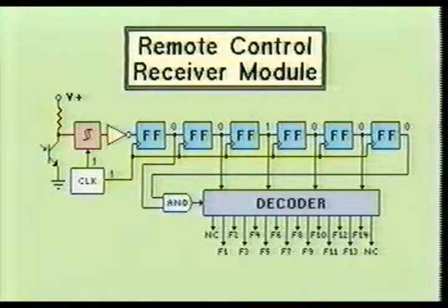The circuit scenario just explained is one of many possible methods manufacturers use to decode infrared light pulses. For example, more light pulses may be used in the transmission of function codes, which would require the use of additional registers or flip-flops. The first and last flip-flops in our example were used to pick out what is called the identity bits within the infrared transmission. Some manufacturers may use more or fewer identity bits and may group them together. In fact, the identity bits could be placed anywhere within the infrared transmission.